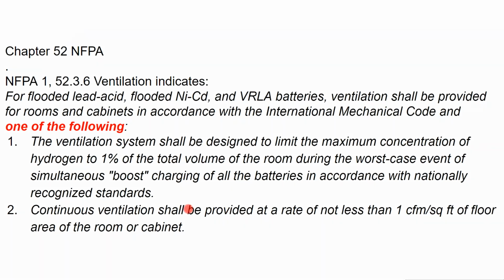And then, to have the most stringent safety considerations, what is standard in International Fire Code but not part of National Fire Code would be to fully enclose the batteries in a cabinet and then have a small fan running continuously inside that cabinet.